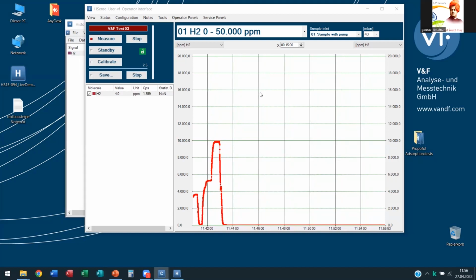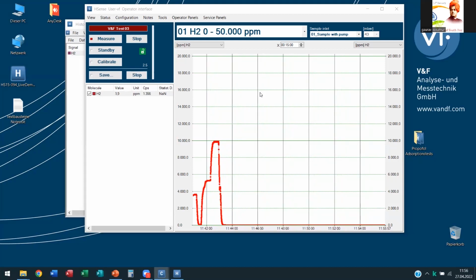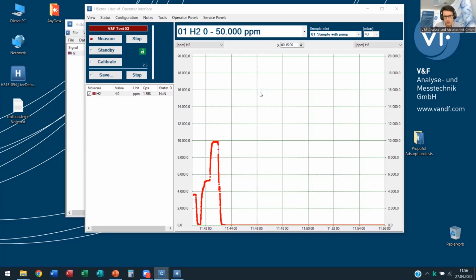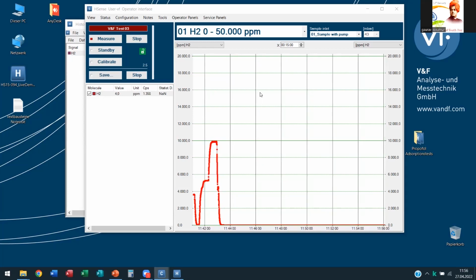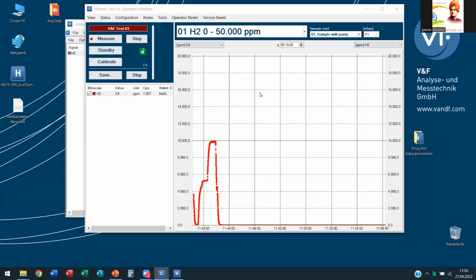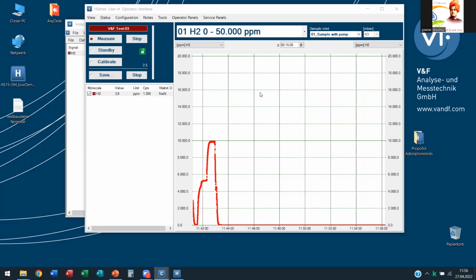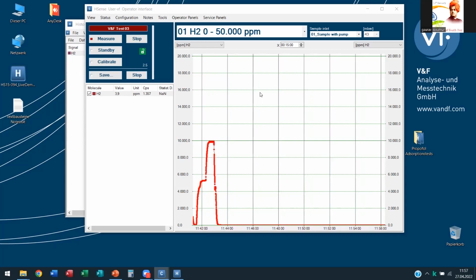No, actually, I just wanted to say that we will be continuously measuring the hydrogen content from the engine exhaust. But after the measurement, there will be a possibility that water content or some dirt or dust, or we may even be using some impure gases which may have some dirt in them, and that may cling to the sampling line. So this needs to be cleaned all the time.